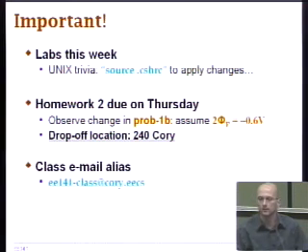So for those of you who are still not familiar with the Unix environment, here's a pretty useful hint: you have to source your CSHRC to apply the changes once you make some changes to your CSHRC file, or you can log out and log back in. That has the same effect. And over here you would need to make some changes to set up the right path to be able to run Cadence software.